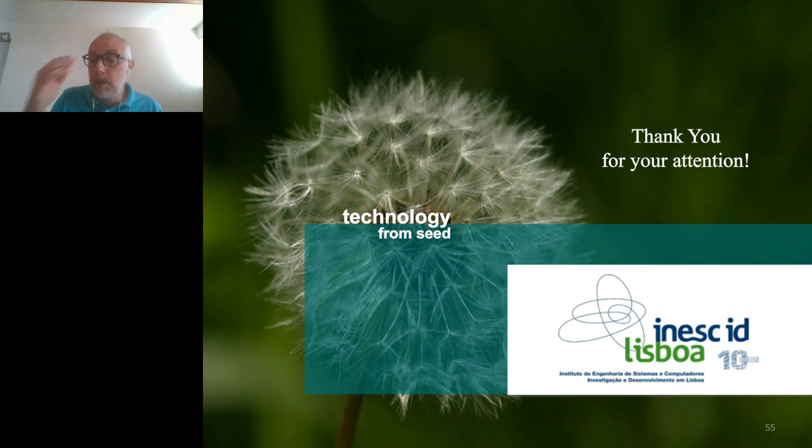So what we do in this case is either you are conservative and you define a range that is large enough to accommodate all the computations that you have to do, or you use some kind of redundant residual number systems, which means that you have an illegitimate range that you keep for the case that you have overflow in the legitimate range. But you pay for it because you have to make the algorithm a bit more complex, and you have to implement it in hardware. So the answer is, in this type of unconventional number systems, at least for part of them, it is more difficult to detect overflow.